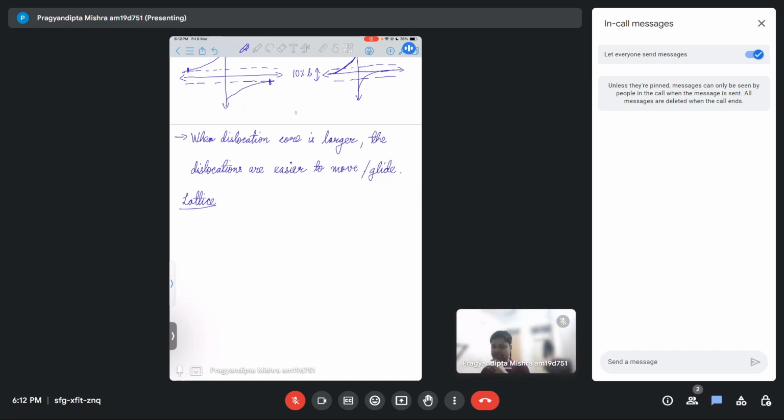Essentially, when a dislocation is moving, there is a sinusoidal resistance present when the dislocation is gliding. The sinusoidal comes due to the dislocation translating from one atom to another and the presence of atoms in between. Those atoms will resist dislocation motion in some form. There is no need to go deeper into how that resistance comes into play, but it is due to the lattice structure, how atoms are arranged within the lattice.